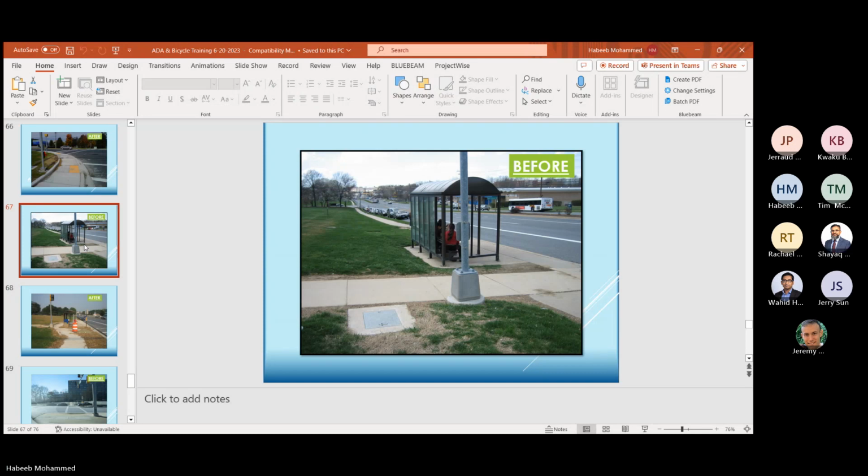Okay. Yeah, I think the landing should be right next to the push button, right? You can clearly tell that the panel sidewalk next to the push button is a panel. It doesn't show you that you have a ramp over there, basically. The push button itself is way too far from the roadway anyway, like 10, 15 feet from the edge of the roadway.